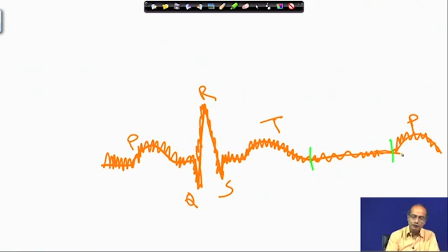Okay. Now, if we want to get the desired signal, the ECG signal in this case, how can we approximate it? We can fit it with a straight line, and then to reduce the effect of noise, we can use straight line approximations, a few line segments to approximate each of these.